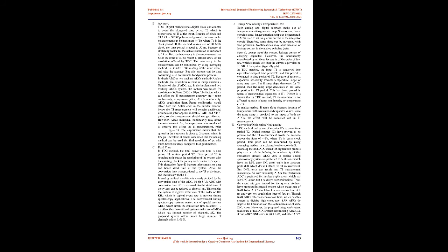See dead time. In the TDC method, the total conversion time is time period T1 plus time period T2. Time period T2 is stretched to increase the resolution of the system with the existing clock frequency and counter IC's speed. This elongation factor K increases the conversion time and hence the dead time of the system. Also, the conversion time is proportional to the TI at the input, and increases with the TI.